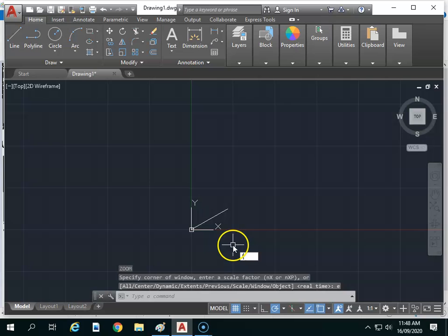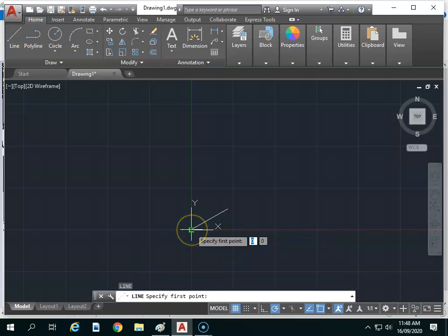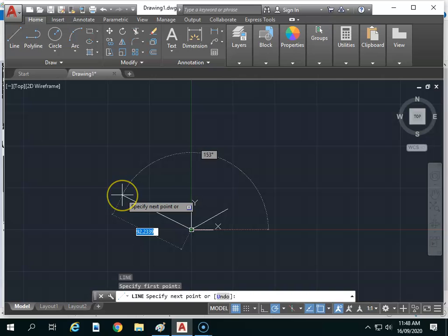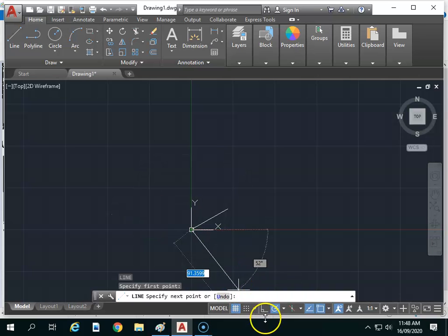Okay, I'm going to draw a new line. I'm going to draw L. Now I could specify 0, 0, but I've got snap on. So it is snap options. Where are the snap options? Here, I think, are our snap options. Yep. So we can restrict it to only. We can set the angle specifically here. We'll play around with that later.